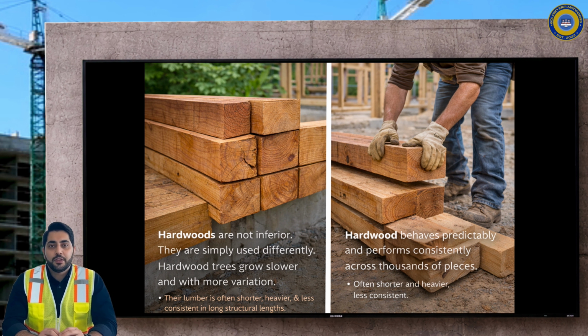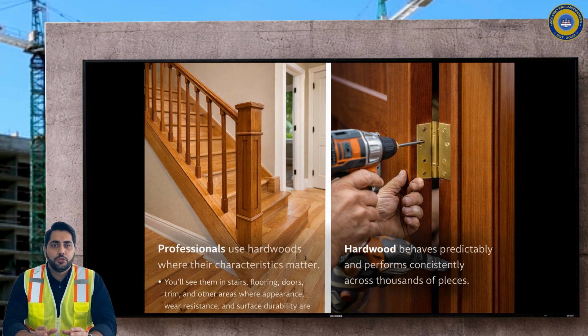Hardwoods are not inferior. They are simply used differently. Hardwood trees grow slower and with more variation. Their lumber is often shorter, heavier, and less consistent in long structural lengths. That makes hardwoods less practical for framing entire buildings, even though many hardwood species are technically stronger. Professionals use hardwoods where their characteristics matter most. You'll see them in stairs, flooring, doors, trim, and other areas where appearance, wear resistance, and surface durability are more important than long-span structural behavior.